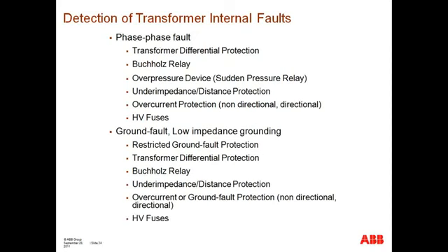Now, how are faults detected inside of the transformer? Here I just have a quick overview of some of the different elements that are utilized for transformer protection. So in the case of phase-to-phase faults, transformer differential protection. At the top of the lids, Buchholz relays in the case of internal faults that occur below the oil level of the transformer.